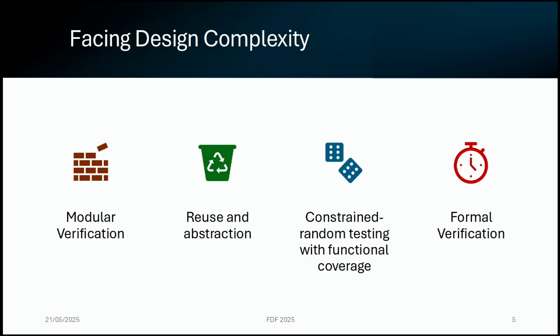And the last bit is use formal verification if you can. Formal verification can have a very big return on investment. The investment is big as well, because bringing up a formal verification environment can be quite time-consuming. And the other nice thing about formal verification is that it's not just going to provide a full proof, at least in the early stages of your design, but it will also complement the simulation base. Because if you find a bug in formal that you didn't find with your stimulus, it means that some of your stimulus are missing, or maybe some checkers.